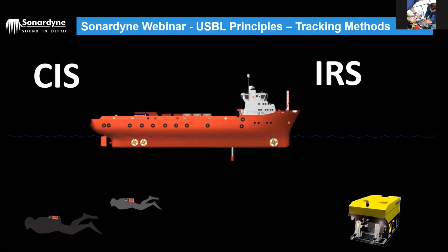They all wait their turnaround times, and then they respond after their turnaround time. And this is why that turnaround time is quite important, because we can program on the fly, even whilst underwater, we can tell these beacons what their turnaround time should be. They're programmed before they go in the water, but we can change it on the fly. So if we realize that two signals are arriving back at the transceiver at the same time, the system is likely to miss one of them. Because if you've got like 8 beacons down there you're trying to track in common mode, it is achievable as long as we have 8 different responses coming back at different times at the transceiver.